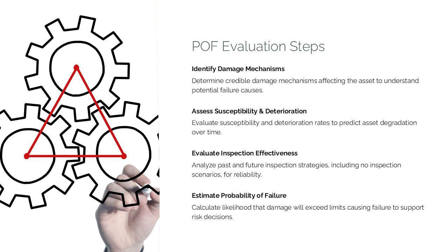This slide explains that the evaluation should consider both current and future operating conditions and may involve assessing multiple inspection strategies, including scenarios with no inspection. The outcome is a defensible estimate of POF for each damage mode and time period, supporting informed RBI decisions.